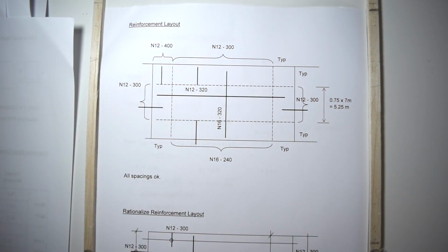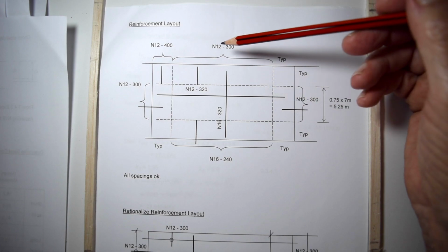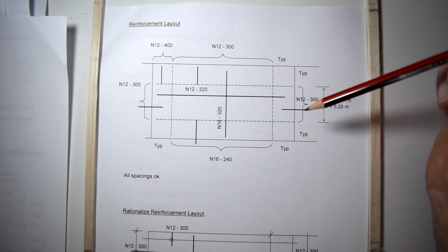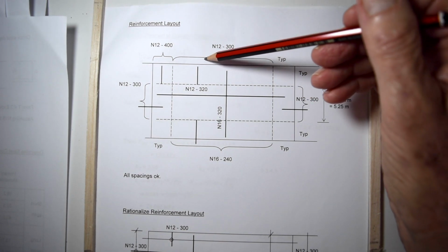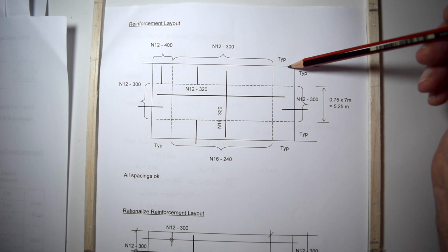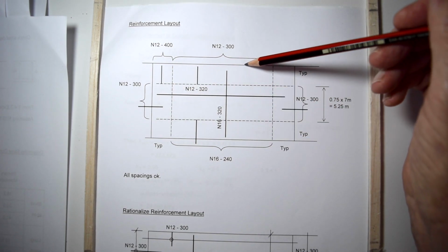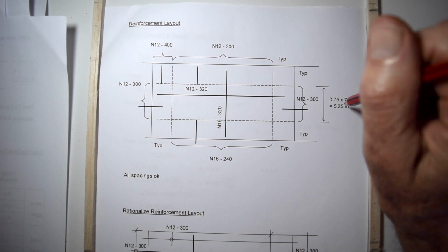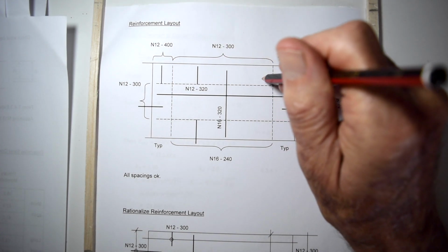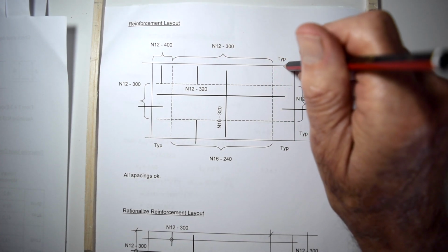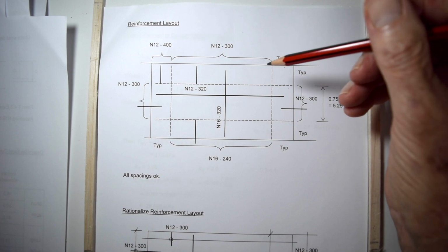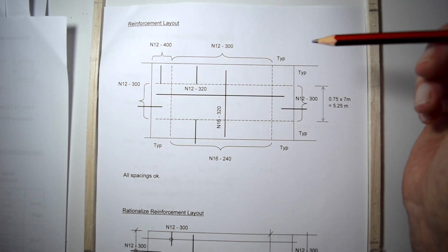Right. We now do a basic reinforcement layout based on the figures that we got from that last table where we did the calculations for steel areas. This line there is the outside, or call it the center line of the slab. Okay, 14 meters by 7 meters. We're taking 0.75 of that, because that's that area. As I said to you, the positive moments outside of that width plus that width are very small, negligible, and the same in the long direction.